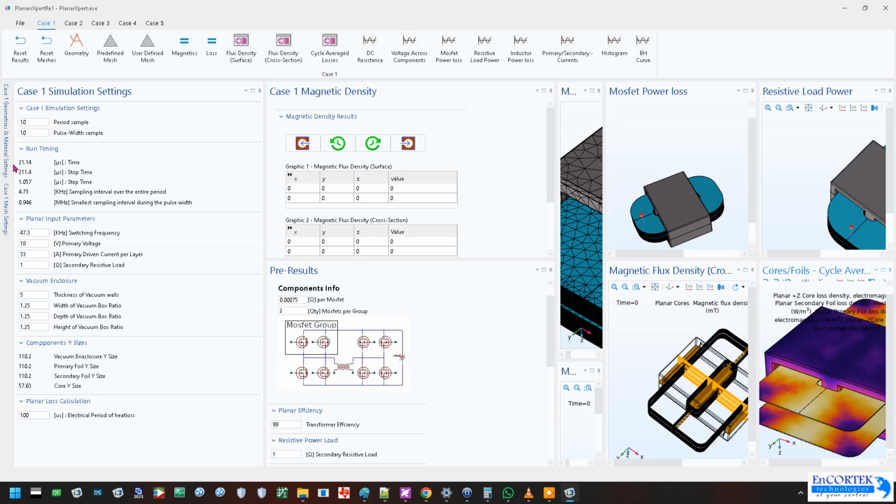So if you're running a certain simulation for a certain period, we see we have a stop time of 111. I will write some code to not allow it to cross this time. I will leave this box and put in a slider as well, and whatever time we have available we just put it at max here, and we run a simulation with time minimum.